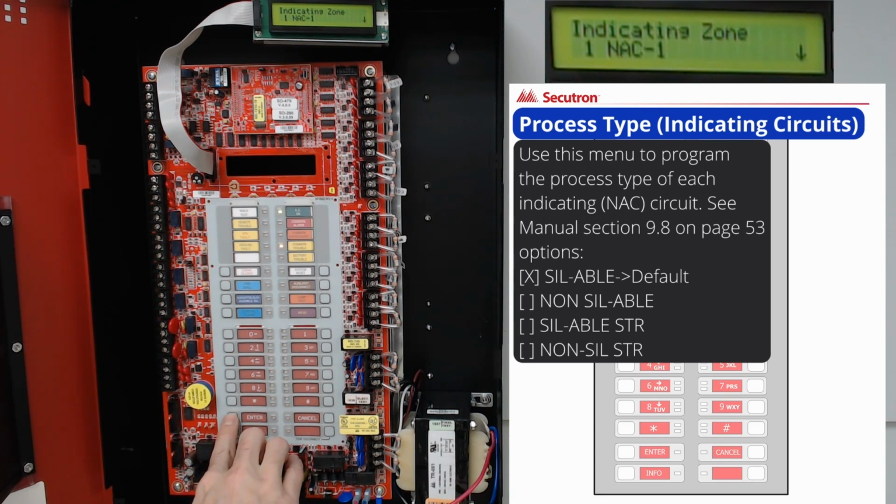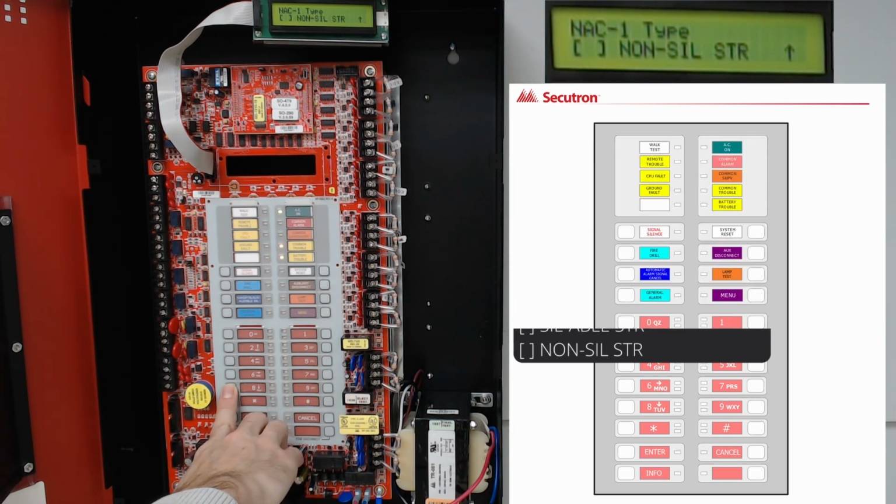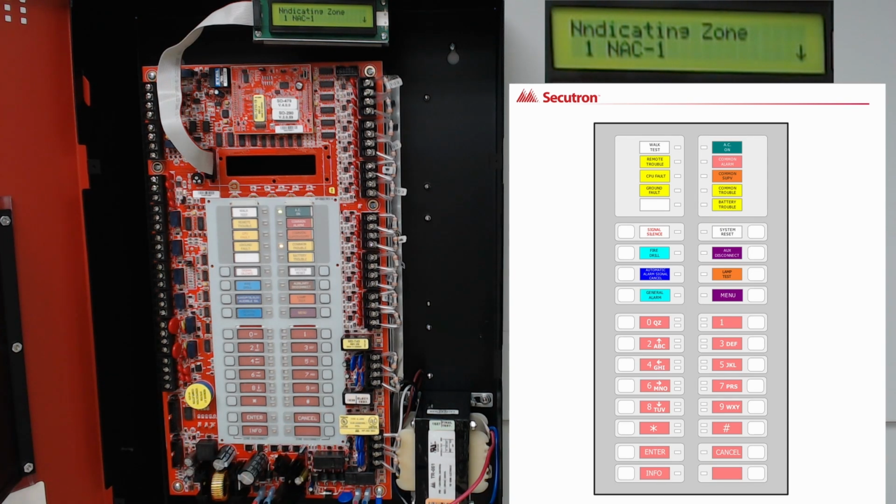If we select enter on one of these indicating zones, we can see the options for it. By default, the NAC 1 has been selected and all NACs have been selected for silenceable. However, if we press the down cursor, we can find that we can have it selected for non-silenceable, silenceable strobe, and non-silenceable strobe. When we find the desired option, we can hit the left or right cursor arrow to apply the X, hit enter, and then cancel to exit back out to the previous menu option screen.